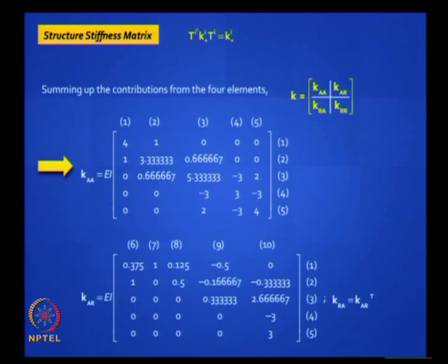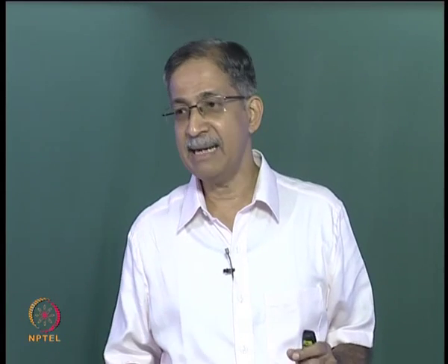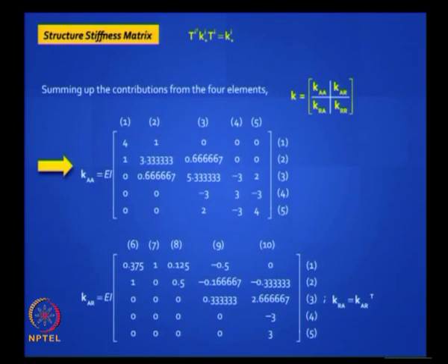Another thing to look out for is, if any of the diagonal elements is close to 0, you have got an ill conditioned matrix. Inverting that matrix will give you a lot of errors. Normally it will never happen, okay, because luckily for us, in linear elastic structures, the stiffness matrix, unlike the flexibility matrix, is guaranteed to be positive definite and well conditioned, okay, right. Any questions here, is it clear?